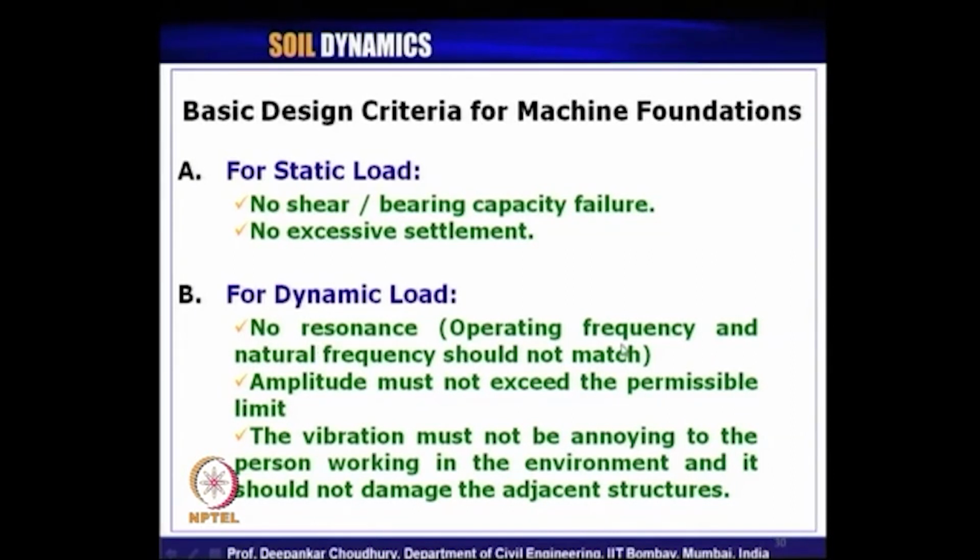The operating frequency of the machine must not match with the natural frequency of the machine plus foundation system. So, when we are talking about the system, when we are designing the foundation, we are not only talking about the foundation itself, we are talking about foundation plus machine together, because the entire assembly is going to vibrate together.